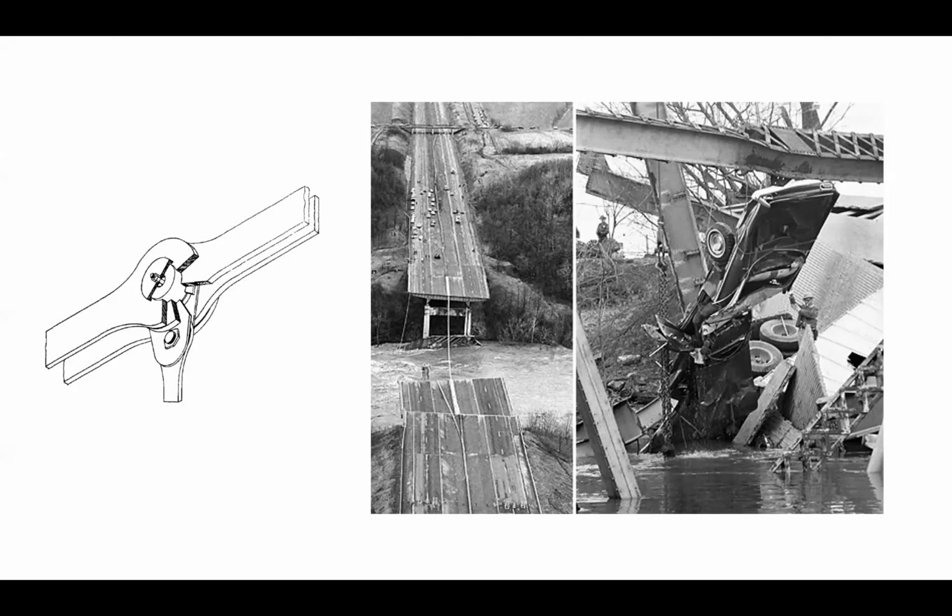And so this created the Bridge Inspection Program, where bridges are inspected every 24 months. It established criteria for recording all of the information about the inspection into a national bridge inventory. It established criteria on the inspectors, team leaders, who's qualified to do inspections, and the program that you have to set up for bridge inspection. So this really kicked off all the federal guidelines that are still in place today.